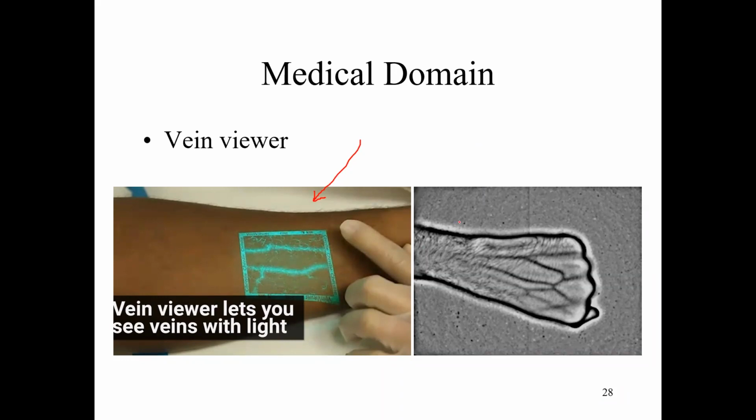IR, right? Infrared camera. So any camera is nowadays an infrared camera, right? Because it should be a CMOS sensor or maybe a CCD sensor, right? Mostly CMOS sensor. So CMOS sensor has some kind of sensitivity for the IR, and if you remove the IR filter, because almost all the cameras, including your iPhone or maybe Galaxy phone or whatever Android phone, whatever it is. So all these smartphones come with a camera, CMOS sensor, and on top of that you have an IR blocking filter.